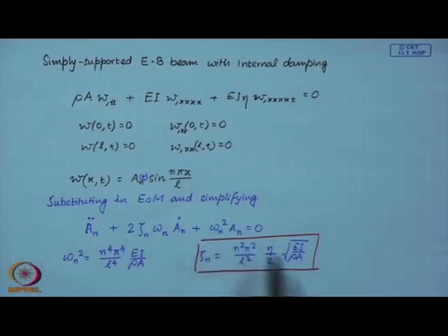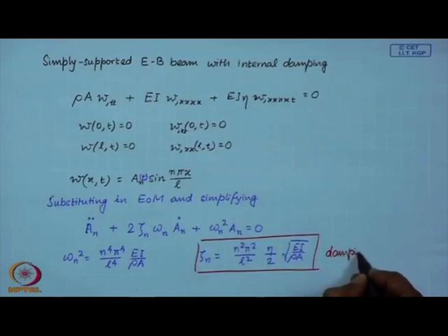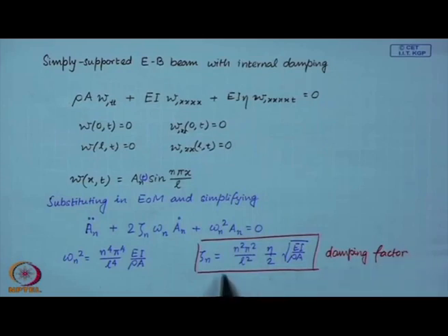there is a damping factor which we find is proportional to n square. So, the higher the mode, the higher will be the damping factor. Which means that the higher modes get effectively damped because of internal damping.